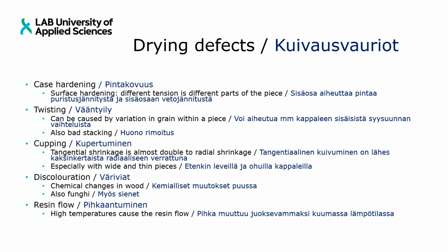Cupping is also typical for timber. It's not actually a defect. It is just something that happens with it. But again, that's all to do with shrinking and tensions. You will learn that when we talk about wood technology. And again, remember, you have cupping especially with wide sections which are thin. They tend to cup the most.